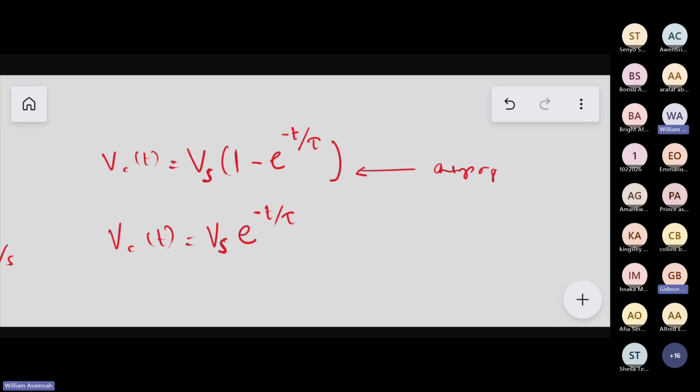A debounce RC circuit, R equals 10 kilo ohms, C equals 10 microfarad, is wired across the switch input. When the switch opens or bounces, the capacitor discharges through R, maintaining stable high voltage at the PLC input for the duration of the bounce. The PLC only sees the bounce-free settled signal.